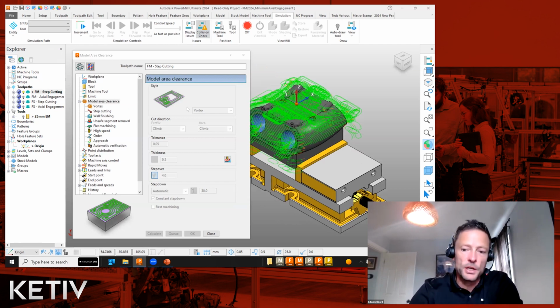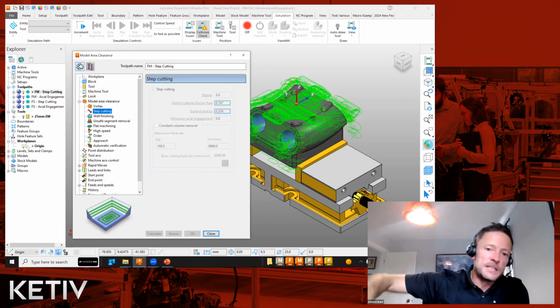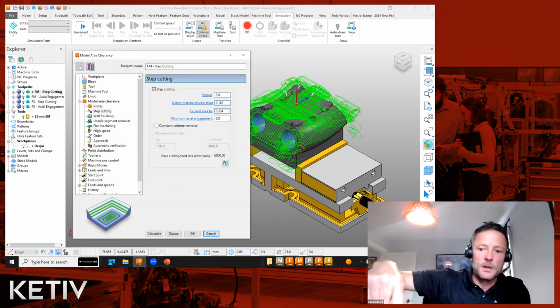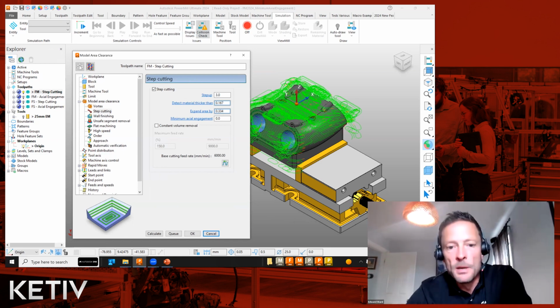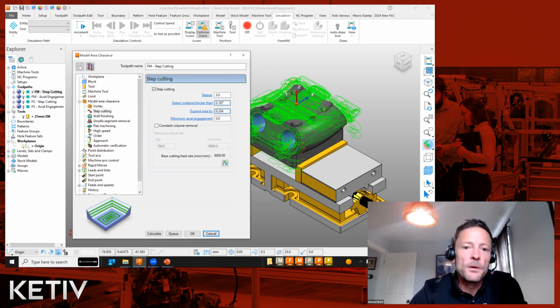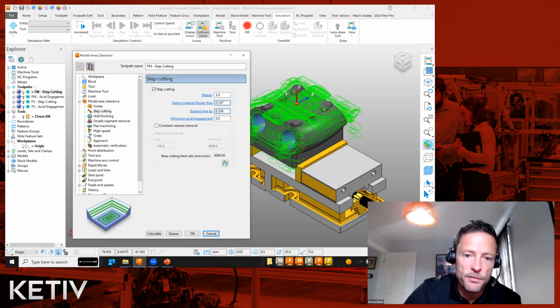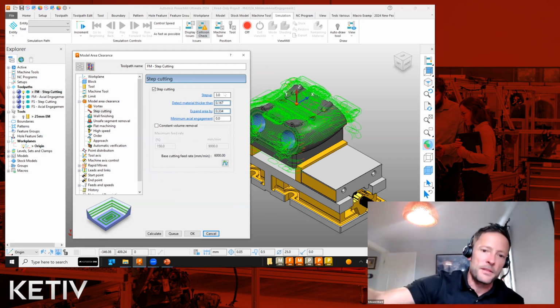value. Now, what that's going to do, obviously, with the deep depths of cut, the tool's then going to go back and really tidy up, you know, the stair effect in a way. But what you could get a lot of the time was it would really be picking up on small fragment toolpaths. Now, with the addition of this minimum axial engagement, you know, we want the step cut to be 3 millimeters, but before it could be anything pretty much up to that 3 millimeters.